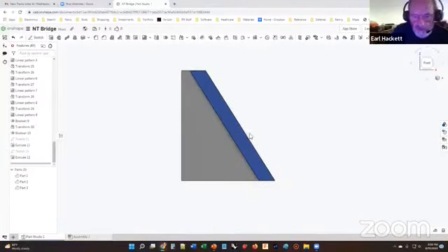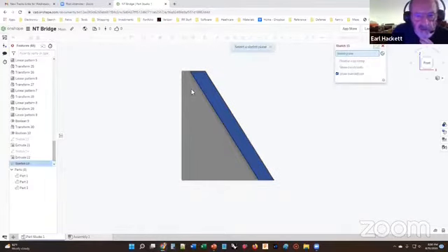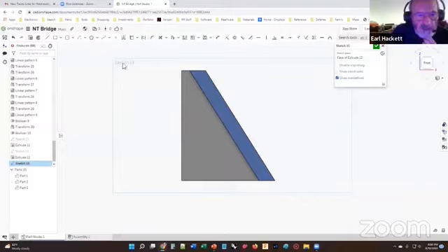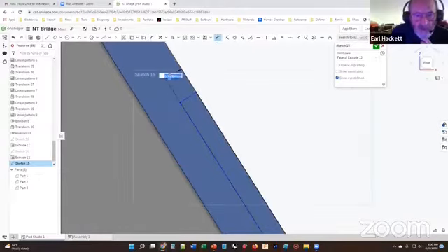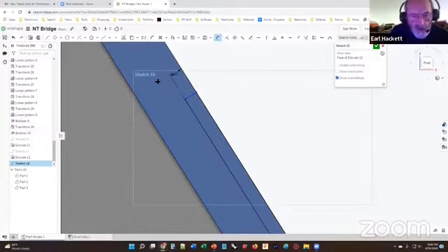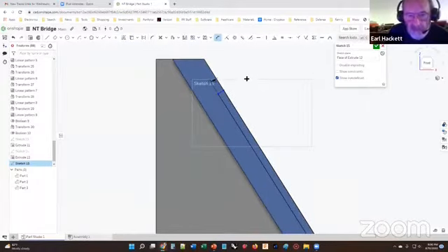We're going to put the flange on this guy here. So we're going to go back to a sketch. We're going to sketch on this surface here. And we'll again do the aligned rectangle. And we just set up this one measurement. That's 0.25. Never had a power failure like that before. So we want to go to extend to right here.